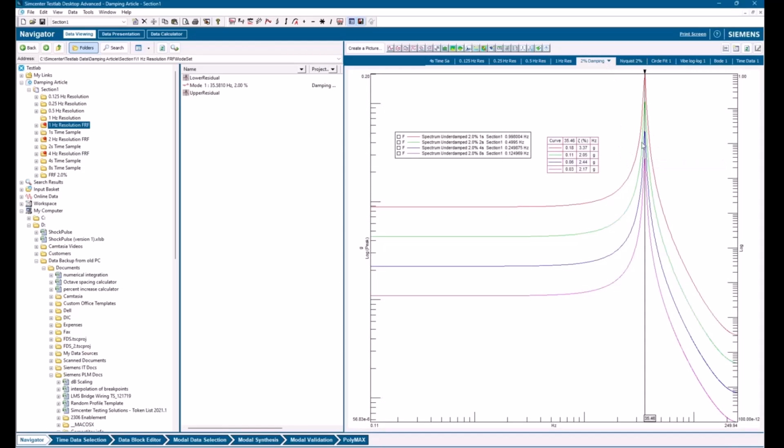So you can see this result is an approximation, and sometimes a wildly different approximation than what the actual system damping is. So you have to be careful, right? So very, very dependent on frequency resolution. But that's how you would display the damping value from a cursor. So that is everything I wanted to talk about.